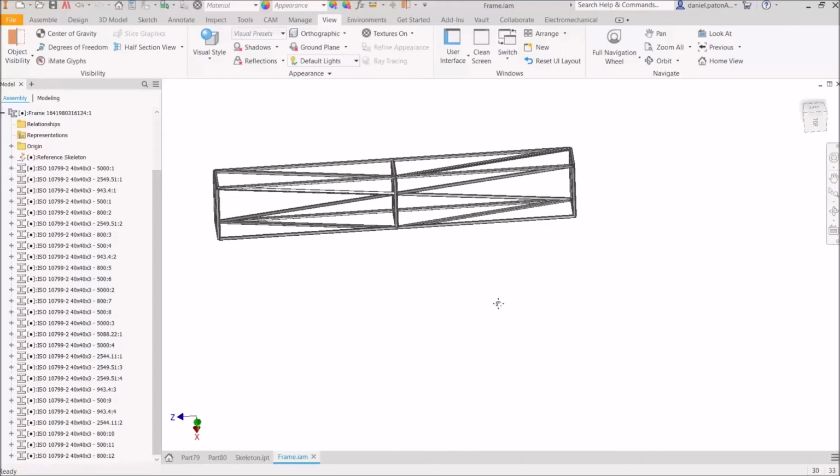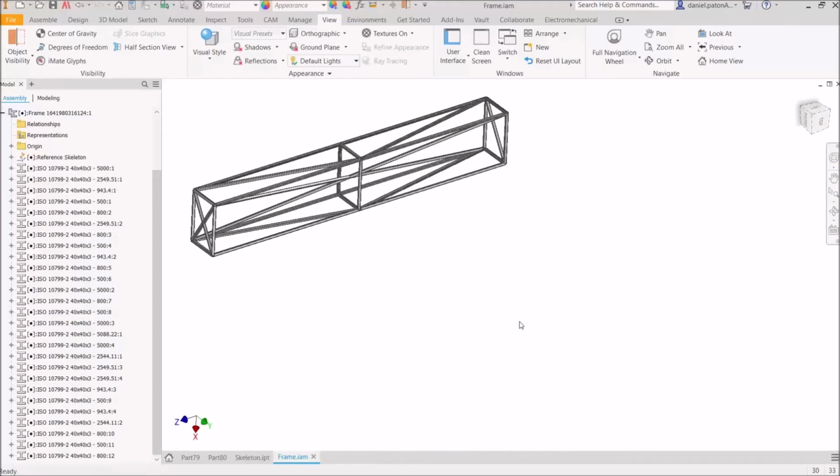So my advice, just from previous experience, would be have some anchoring points, either from some 2D sketches or some work planes or some points that you've locked in space, and then link your 3D geometry to that, connect your 3D geometry to that. You can also do it in an assembly environment as well, where you can actually project out some of the points from the 3D assembly and then create your 3D sketches from some of those points. And I'll show you that in an example soon.